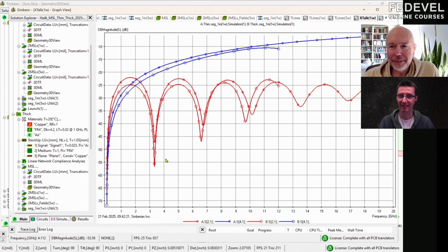So basically, the result of what we are looking at: on the standard two-layer PCB with thick dielectric we are getting similar crosstalk, but the distance between tracks is much larger, 2 millimeters or 80 mils, compared to the example where the reference plane is very close under the track, only 100 micrometers or 4 mils. Then the space between the tracks is how much?